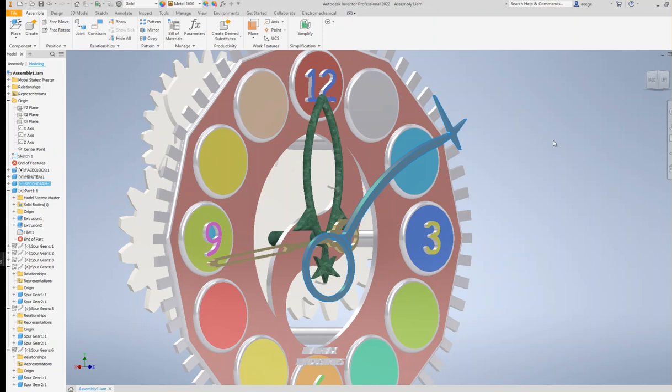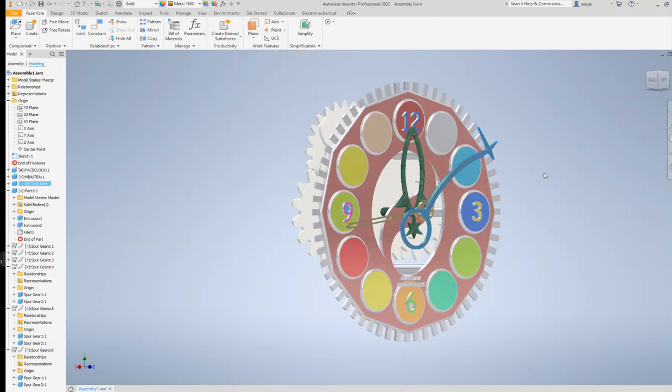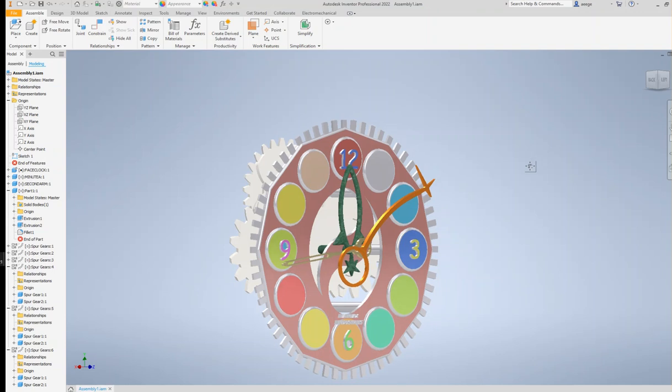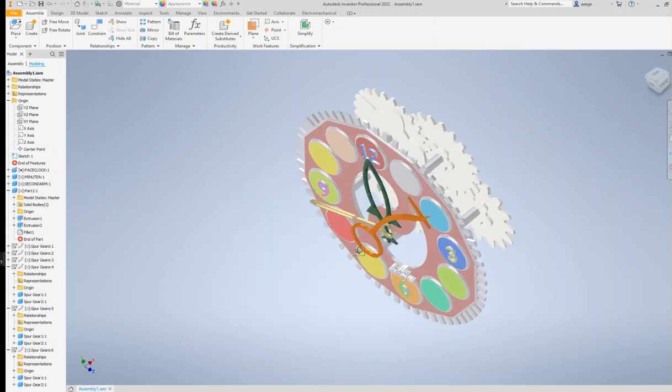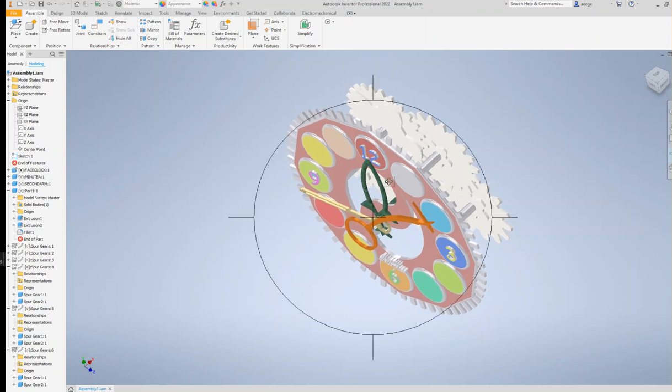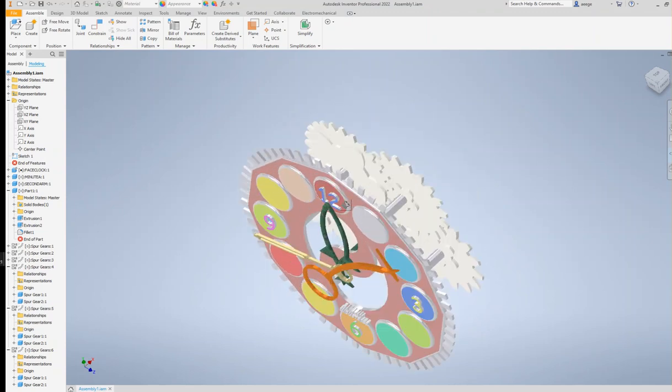One of the things you would like to do is change your point of view by making it a little bit smaller, and perhaps pressing your thumb wheel and centering. I'm pressing the thumb wheel, moving and panning down, and perhaps you should be using your orbit command to look down from 12 o'clock, and then zoom in a little bit better. There it is. Press the right mouse button and get out of the orbit command. Orbit is a very useful command, and what I'm trying to do is create another constraint.